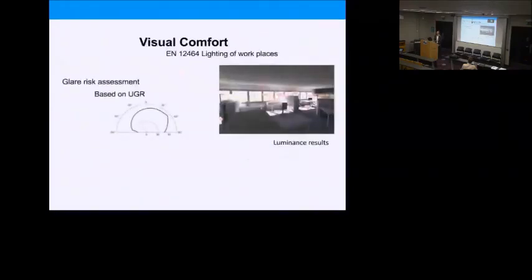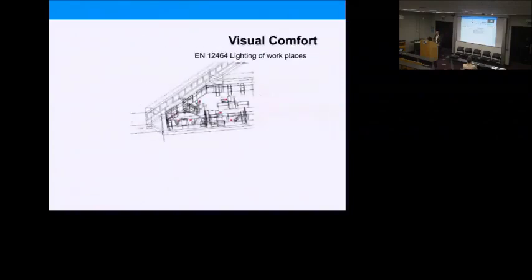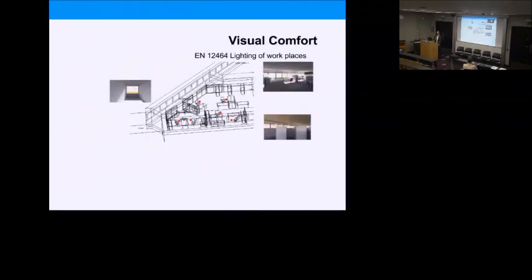We also address visual comfort, in this case glare risk assessment, for people who feel that the space is too bright. This is particularly important in large offices where nobody controls the blinds, which are automated. You would like to see if there's a problem there, and you would change the set points of those blinds. Again, for each one of these positions, you're going to have a dedicated radiance simulation. For consultants, this is very specialized work. Let's do glare risk assessment. And in this case, you can do that without any knowledge of simulation.